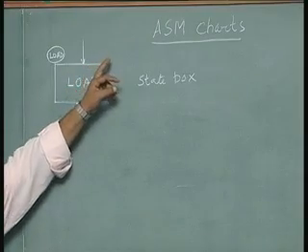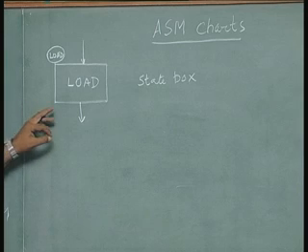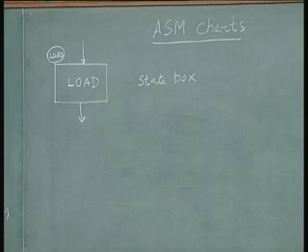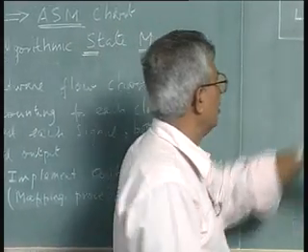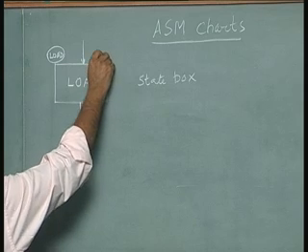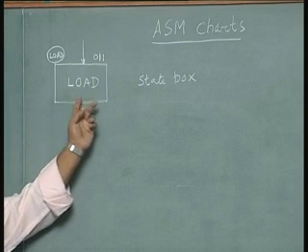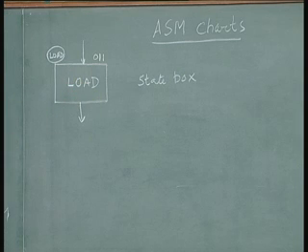And in the right hand top corner, again outside the state, you give the binary state assignment. Each state in a state graph needs, depending on the number of states, a number of variables, and each of those variables will have a 0 or 1. So we have a binary number representing each state, and that number is given here. For example, I will call this 0 1 1, for no specific reason, just arbitrary. So 0 1 1 is a binary value of the state variables of this particular system.